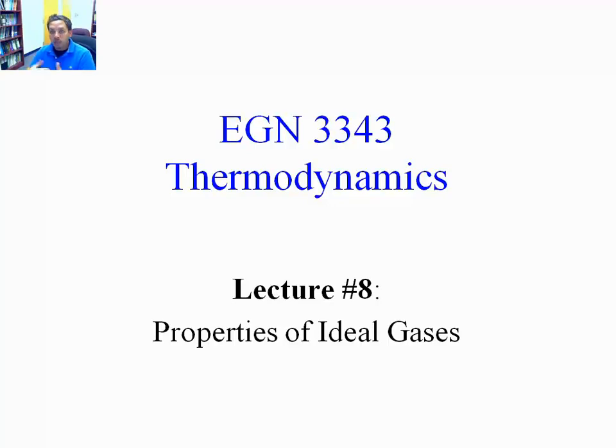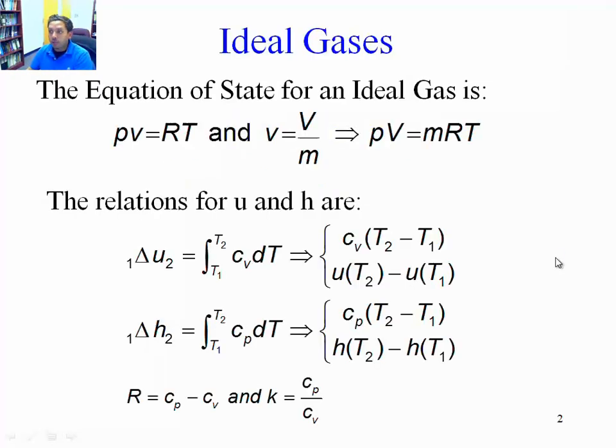Their normal state is as a vapor. We know oxygen is a gas, we know hydrogen is a gas, we know CO2 is a gas, and CO is a gas. That doesn't mean that they cannot change phase to a liquid or even a solid. We know that we can actually liquefy or condense oxygen at very, very high pressures and very, very low temperatures. But under normal circumstances, they operate way out there, far away to the right of the saturation dome, and they will not condense under normal conditions.